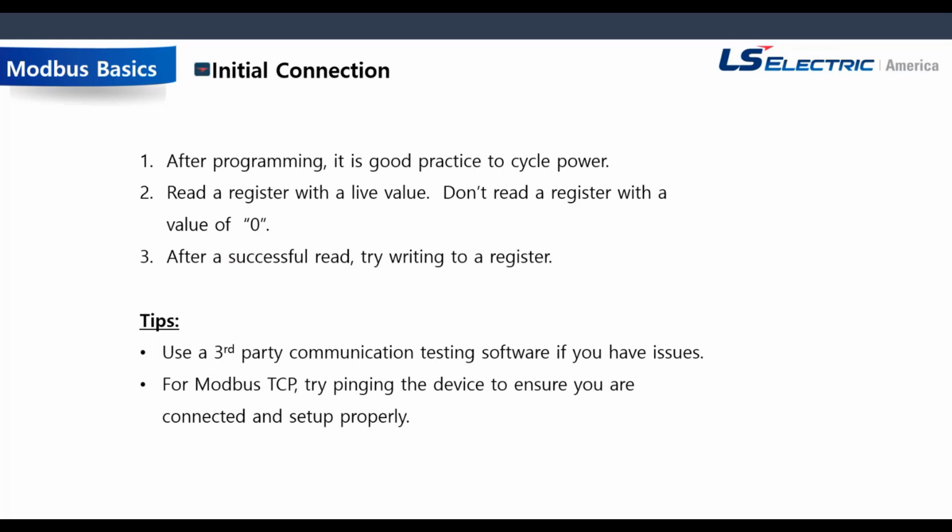It's also recommended, if you have any issues, sometimes guys like to just start using their Rockwell PLC or whatever PLC they're using, and they have all this code running. But there could be some things that are interfering with the communications. So sometimes I'll just say, hey, step back. Let's use a free third-party communication software and let's just try a read. Can we connect to the drive? Are we able to read data? If you're good, then okay, the drive's okay. If it's not good, then you probably have to go back and check those 3 or 4 parameters that we mentioned earlier.